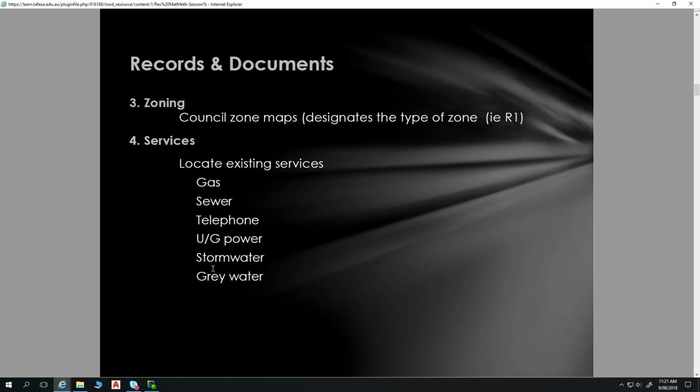Okay. So you may be able to update that grey water. I know you've probably been through all that, but there are pumps that do higher pressure and higher volumes as well, because you've got various different designs of these systems. Some of the dispersal systems are what's called a pressure dose system, where you have all these underground tubes. You actually have to provide a fair bit of pressure in those tubes to disperse the water into clay soils and things like that as well. So certainly there are options for that.